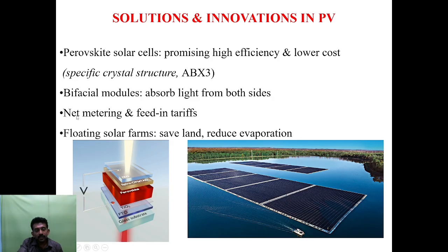And net metering and feed-in tariff is one of the demand side management techniques, in which the customer becomes a major part. The decentralized power generated by the customer is being bought by the electricity boards or the energy markets and fed to the grid at a certain transaction rate. If there is high demand in the grid, the electricity board will purchase the power from the customer and then distribute it to the grid.